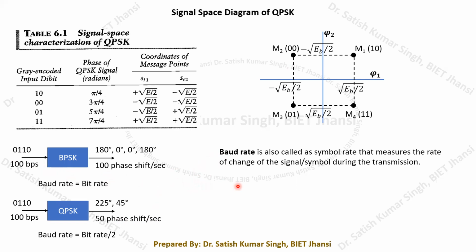At that time these bits will be converted into certain line codes, and these codes will be fed to our transmission line. So how many bits are we sending per second? Say we are sending 1000 bits per second. Then I can say that it is 1000 bits per second we are launching to the transmission line, and that signal is being transmitted.